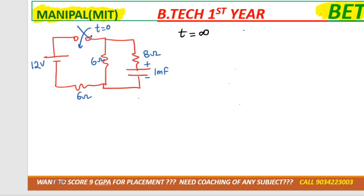The switch is closed, right? So I'm closing the switch. If I close this switch, then the connection will be formed, right? And again the capacitor will behave as an open circuit. Mark the A and B terminals, and we can conclude that VAB would be equal to VC of infinity. That is what we need to calculate over here.